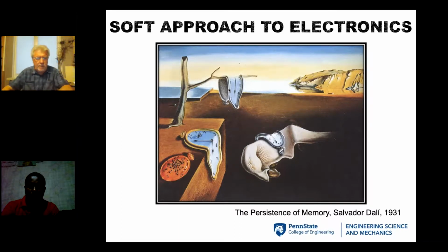And the stretchable property is important when we have to deploy this onto complex 3D surfaces like the elbow, finger joint, or heart, or this type of different 3D surface. And the flat surface can only be applied on, for example, a cone or cylinder, or this type of so-called developable surface, but for the other complex surfaces, it's not possible.